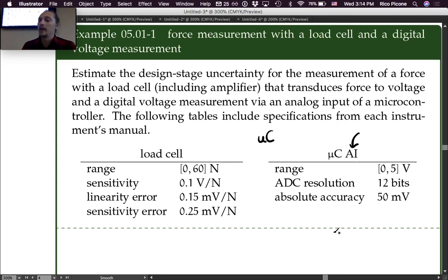The quick and dirty way is to just voltage divider it down, which is totally fine because you are using very high input impedance stuff here, so it's not going to draw any current really. And so probably you're going to just use a voltage divider here. The voltage divider doesn't have to divide it down much, right? Just a little bit. It's only 20% over the range, so divide down a little bit.